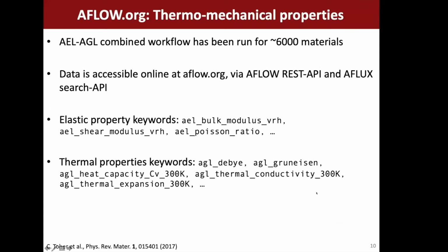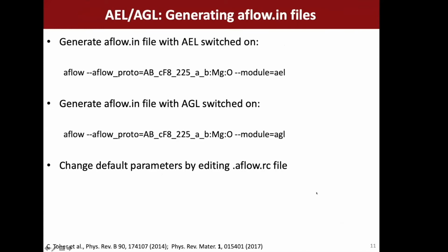Okay, so let's go into the technical details of how to actually run these calculations. Again, we start from our aflow.in file, the files that Dr. Hicks was going through on Monday. Here we can generate an aflow.in file with AEL switched on. Again, we use our prototypes. This is the prototype here for the rock salt structure, and here we can decorate it with different elements.